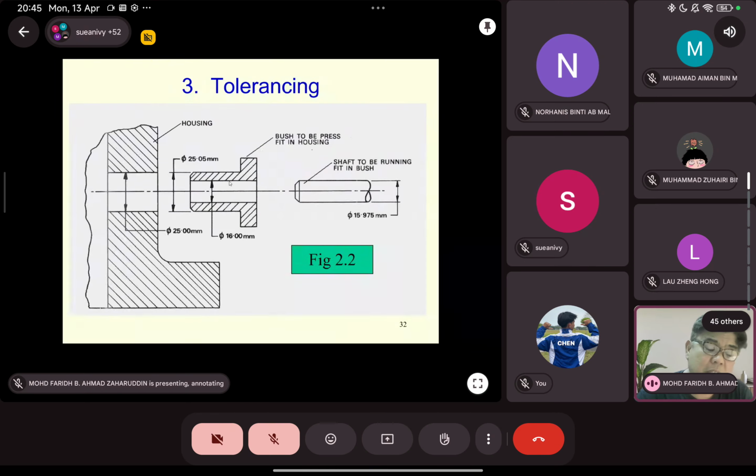Okay, the bush is normally made by forging, by metal forming, so it can stand the high friction. But in normal practice, they use a bearing. But a normal motorcycle doesn't have a bearing, it just uses a bush. No bearing, it's just a bush and wheel hub, which is much cheaper.